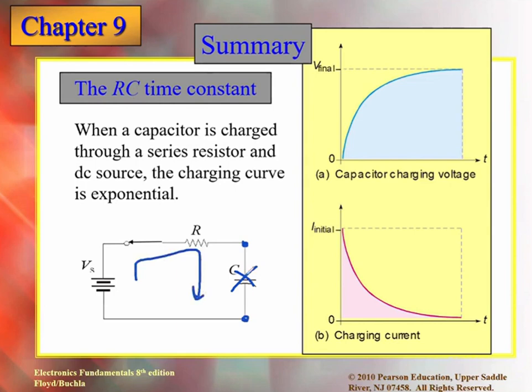So when the capacitor is fully charged, it behaves like what? An open circuit. It behaves like an open circuit. When it is initially uncharged, it is allowing the flow of current, so it basically initially behaves like a short circuit. Short means all current will pass through it. So this is the concept you will learn later on in more detail.